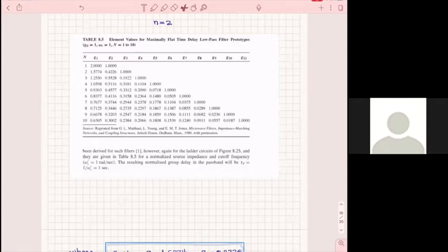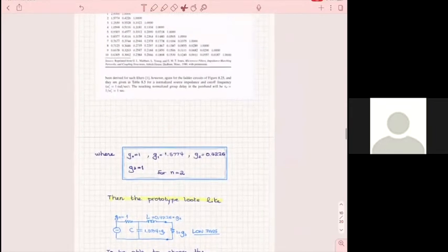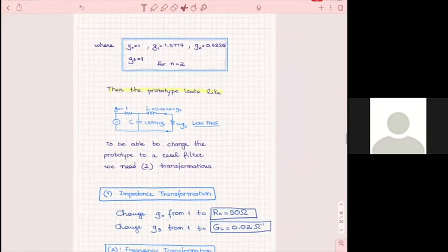So you see when n equals 1 and you have one stage, the 1 is not a stage, it's like the terminating resistor or conductance, resistance or conductance. So stage 2 has 3 elements because the last one is the terminating load, all right? So remember that. Also, make sure you don't consider that as a stage.